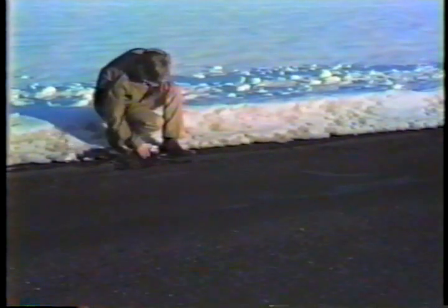Note the water draining from a transverse crack. Heavily loaded wheat trucks were using the road. The thin pavement surfacing near the edge was breaking up due to the weight of these trucks and the saturated condition of the base course. Removal of a few pieces of broken pavement surfacing reveals the top of the granular base course. Note the free water.